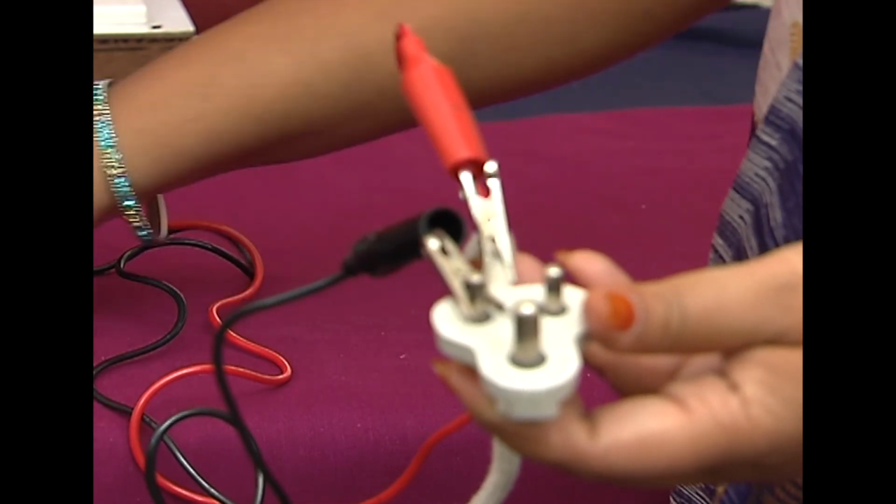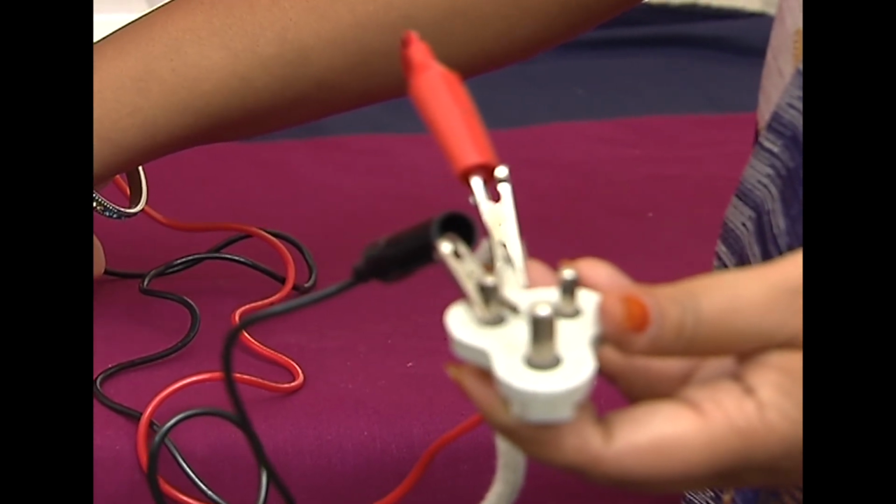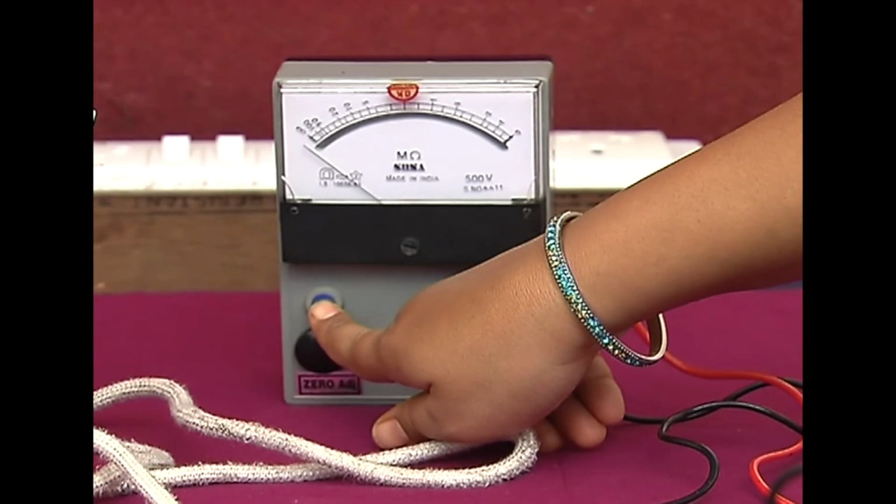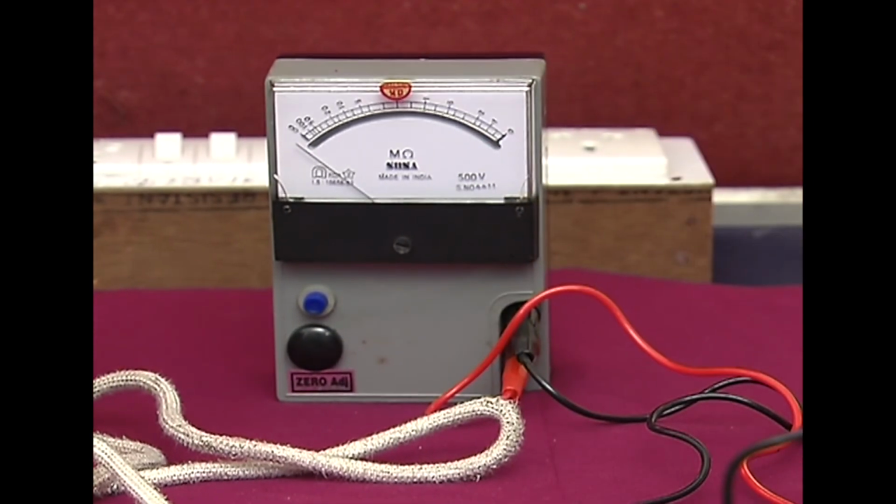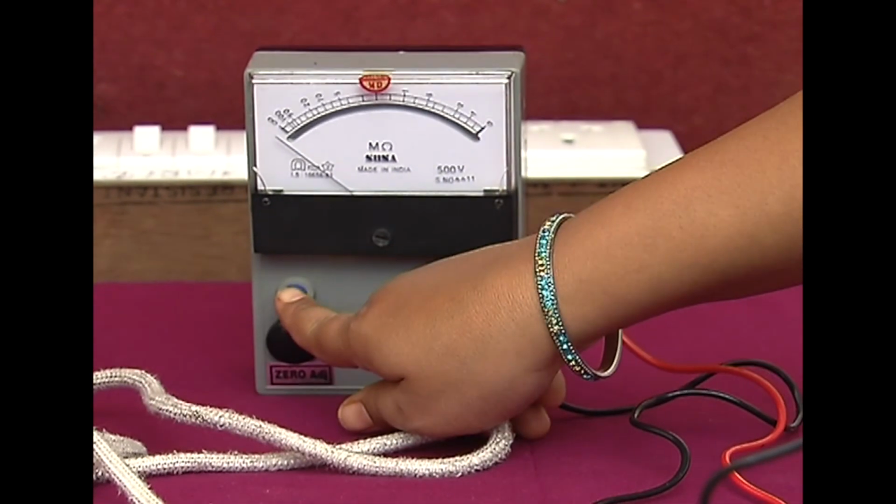Observations and results: when the equipment is in use, the voltage reading should be 230 volts or the voltage marked on the nameplate of the equipment. The discussion is, if there is any change, then it means that the equipment is using either more or less voltage than is required, which may affect the performance of the equipment and also cause failure of the equipment.